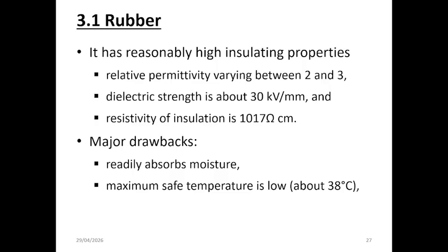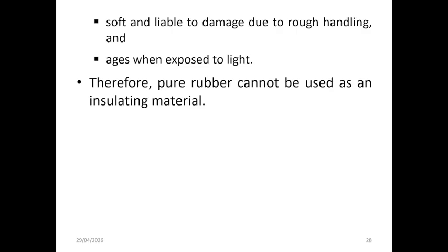So this slide highlights the limitations of pure rubber as an insulating material. It is soft and easily damaged during rough handling, and it also deteriorates or ages when exposed to light. Because of these weaknesses, pure rubber is not suitable for direct use as cable insulation.